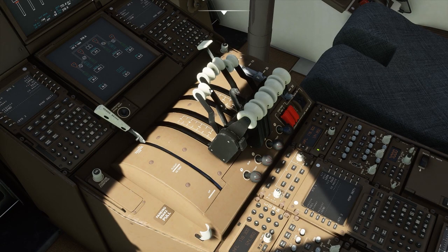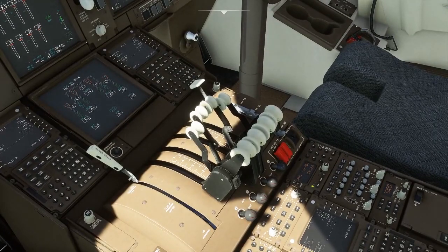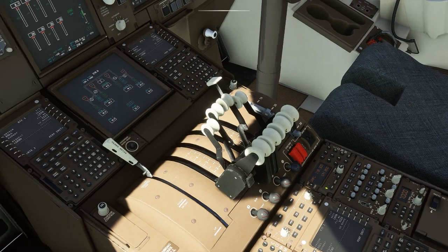So there's normally two stages in reverse thrust on the Jumbo. The first position that you would bring it to, that kind of stops in, is reverse idle, so it means the reversers open but they don't give you any actual thrust, and then you can go to the next one, which is full reverse, and that would give you full reverse in the engines.